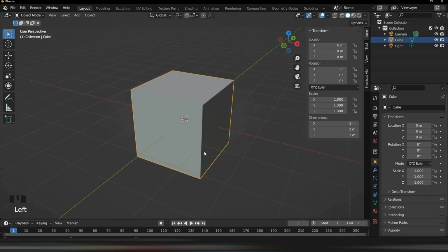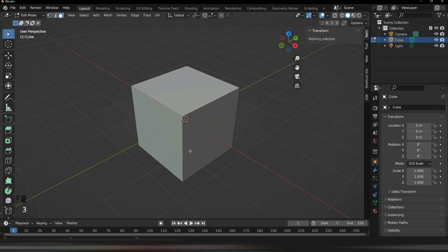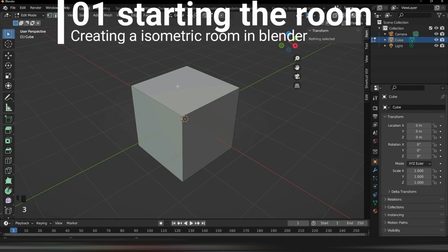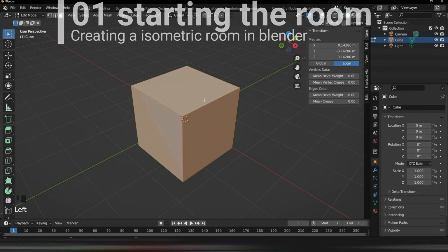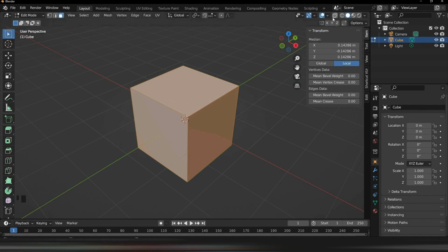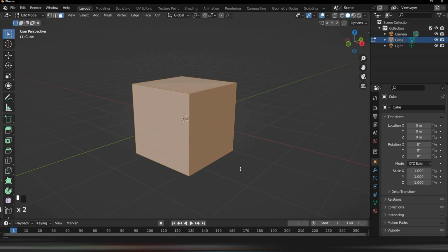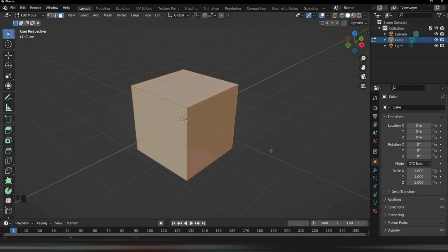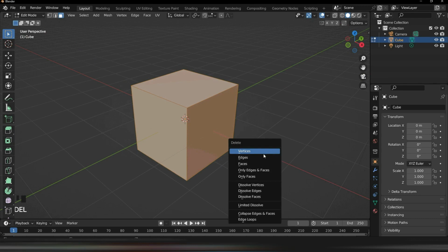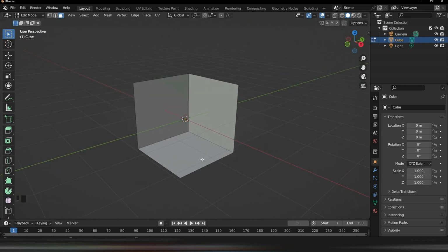The first thing you need to do is click on this cube here. We just go into edit mode. We go into face selection mode, which is pressing 3. And we just select these faces here, not these ones. Ignore them. Don't go into X-ray mode either. By the way, if you're curious, X-ray mode is this. Just for speed's sake. Also, I'm going to close that because it's kind of obstructing vision. But there, you basically select those, and you just press delete, and click here on where it says faces. Okay, so once you have that deleted, you'll be left with something like this.